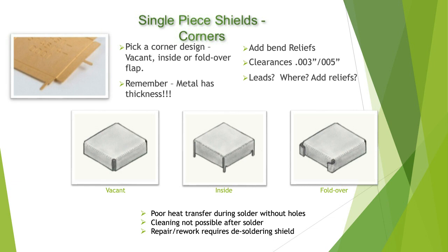However, if you need a little bit better shielding, you can add a little bit extra flap of material to the end of those walls that fold over and around the shorter sidewall. All of those things can be soldered as well if you want to do that, if you want to add the cost. The fold-over design on the right makes the shield a little more rigid. For some applications, rigidity is really important. For most shielding applications, though, thankfully it isn't.